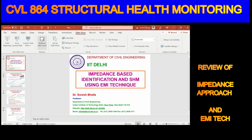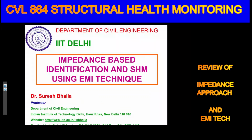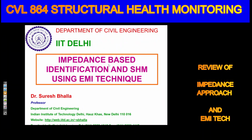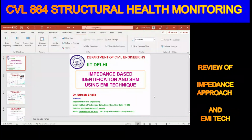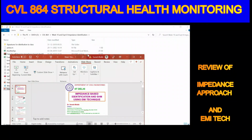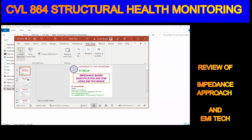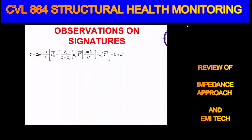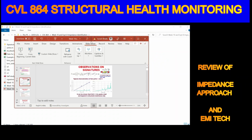Try to understand the basic behavior of the structure, and more important is how they have put the sensors and how they are going to use them. That is the point of your knowing this information. Then you can ask the question: the bridge life would be, say, 100 years or 120 years, what is the mechanism for that? They will be collecting data, using it and monitoring. Is there any baseline signature, I mean, for the undamaged structure?